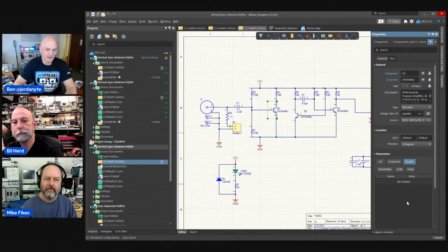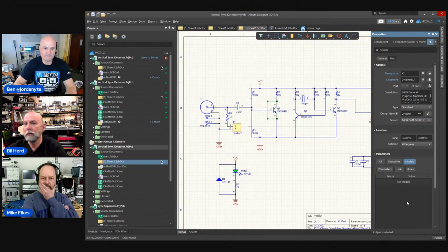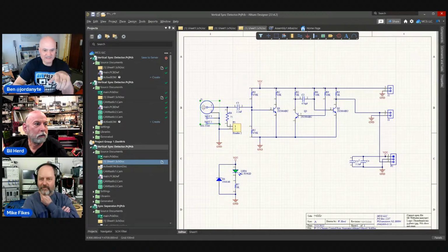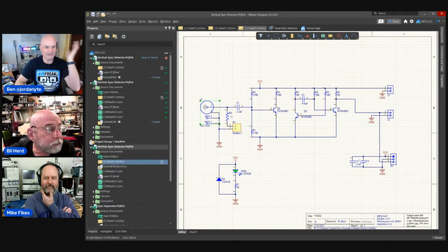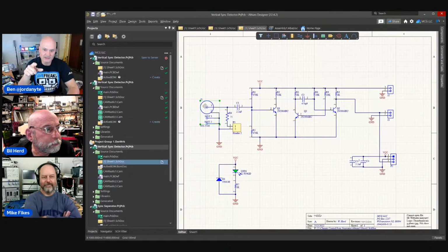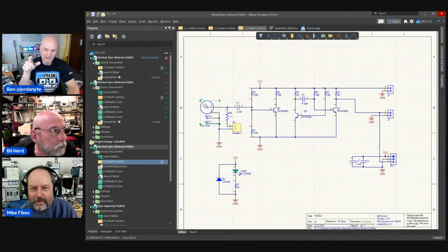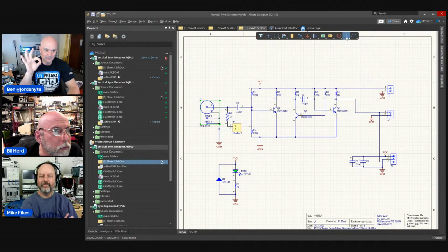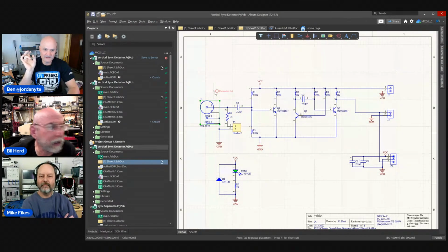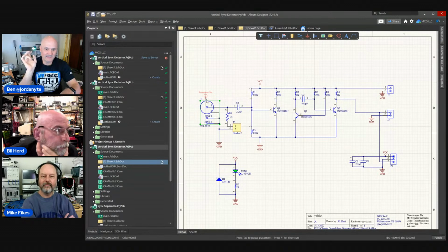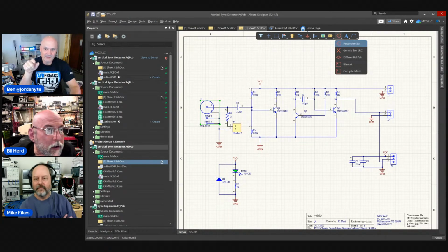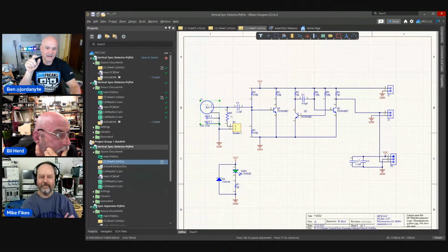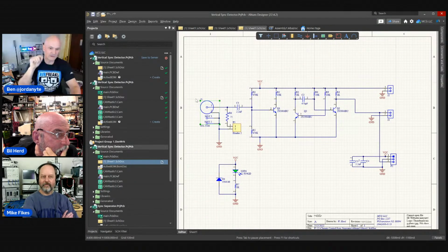So Bill, what you can do is select J1. Say you want to leave that out of the simulation, because it'll stop and it won't simulate if you have a component that doesn't have a model. Okay. So you can't simulate this, right? So what you do is, on the active bar at the top, you see that little eye in a circle pin? Right click on that. That's a parameter set. Hit escape. Don't place that. Hit escape. Right click on that. Now go down to compile mask. Now you cover that component with the compile mask.